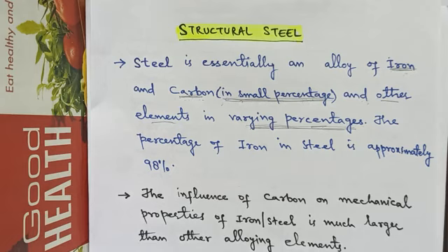As carbon dissolves in the interstices, it distorts the original crystal lattice of iron. This mechanical distortion of the crystal lattice interferes with the external applied strain to the crystal lattice by mechanically blocking the dislocation of crystal lattices, which as a consequence provides mechanical strength to steel.